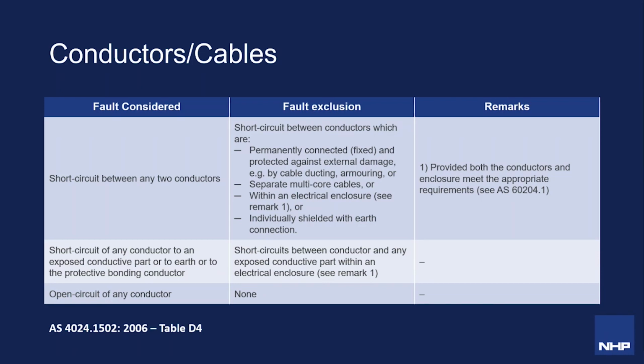I should now mention that this standard has been updated and incorporated into the rest of the AS NZS 4024 series. It's under Part 1204. Or we run individually shielded conductors with shielded earth. One or more of these measures significantly reduces the risk of a short circuit occurring between conductors in the safety control circuit, enough so that we don't have to concern ourselves with any further monitoring for these faults. Thus, we have excluded them.